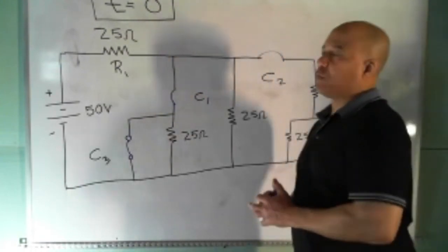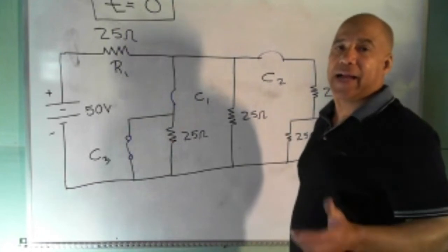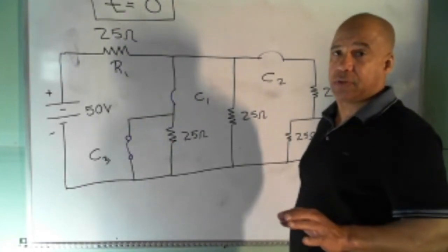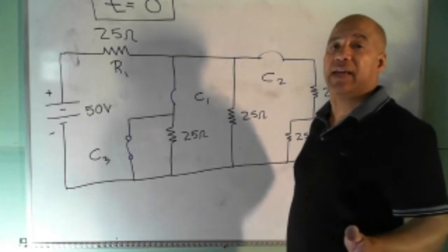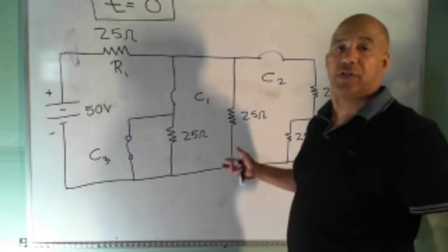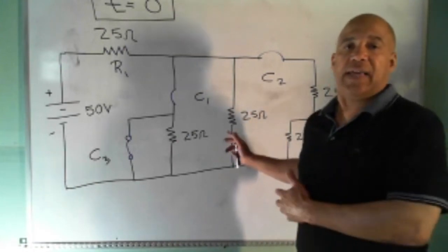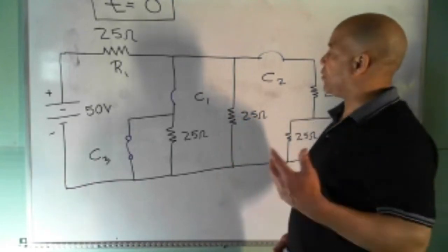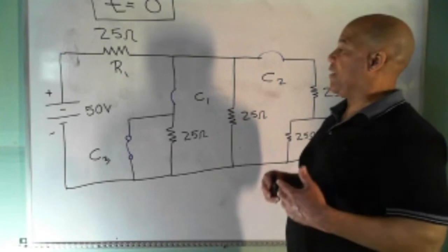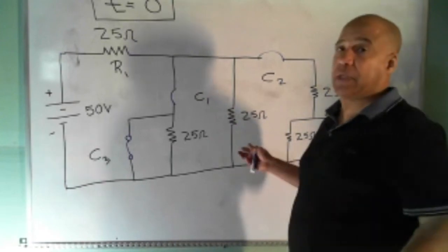Now, guys, what you want to remember, and this is the reason why I gave that quiz on shorts: if I have a short circuit in parallel with anything, whatever's in parallel with it is out of the circuit. A short circuit takes it out of the circuit, makes it go to 0, whatever it is. Whether it's a voltage source or resistor, if it's in parallel with the short, it's not in the circuit anymore.